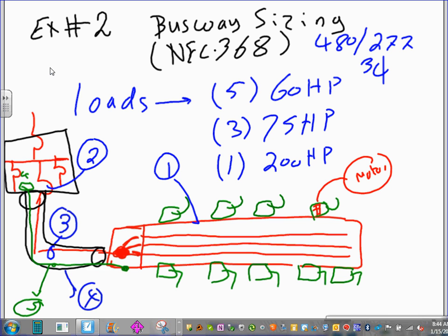The better option is to take a big chunk of power, like 400 amp, in a busway, 6 inches by 6 inches, as long as you want it to go. Bring it up from the panel all over right to the top, and from there you have SO cord. You plug the SO cord into the busway and you go directly to each and every one of these machines. That's the most efficient way of feeding machines on a manufacturing floor. Again, we're going to have a whole chapter showing you that one.